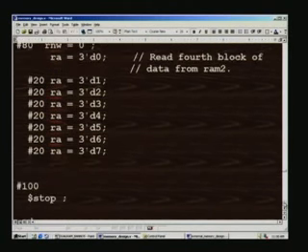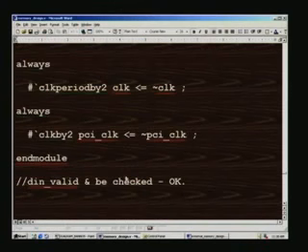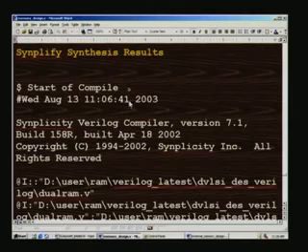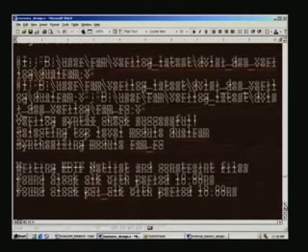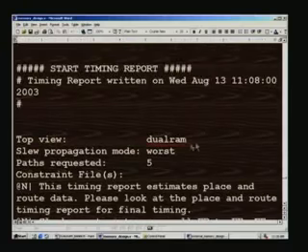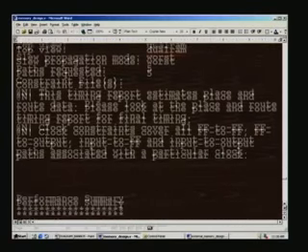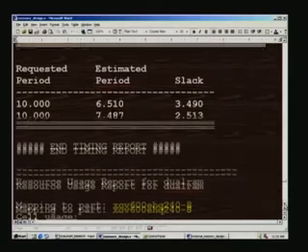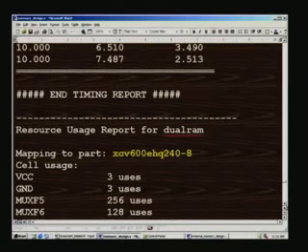And let us have a look. Okay. So, we had 2 clocks, so they had to be taken care of, and that finishes the test bench. Let us have a look at the simplified results here. This is the dual RAM design. So, this is the system clock, it operates at 153 megahertz, and the PCI clock is 133. So, you can safely go to PCI hopefully. Let us not jump to conclusions right now, because we need to see the back annotated results, which will be got only in the Xilinx place and route, right.